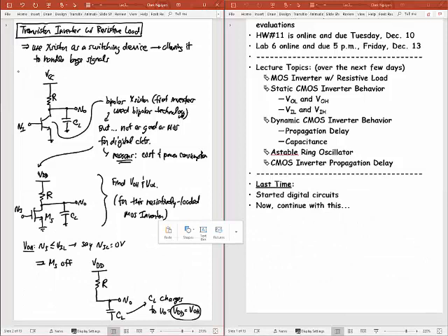And so instead of a bipolar transistor, and the early digital logic used bipolar transistors. This was in the 80s, this was happening. But after that, we quickly went to MOS, because MOS would consume less power and they're smaller. And the first MOS type circuits were like this. You had an MOS transistor and you had some kind of load. In this case, I have a resistor there.